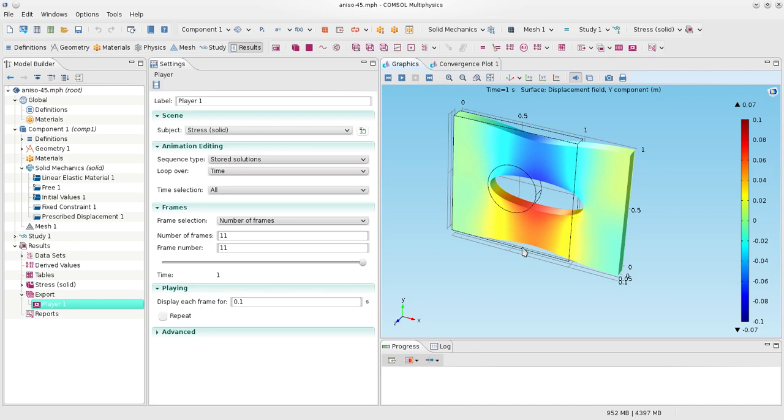But that's a structural effect. The material behavior has no contraction. The material does not contract. It's free to do so, but it doesn't, or it does so very little, because the Poisson ratio is 0. So that's the case of isotropy. Probably no surprise. This is more or less what I would expect to see.